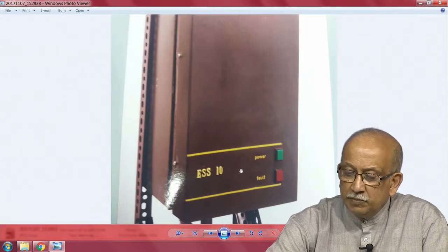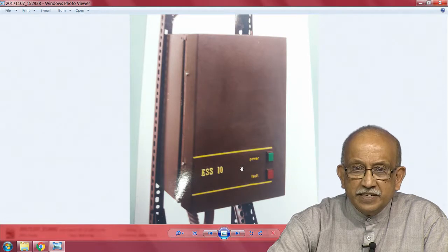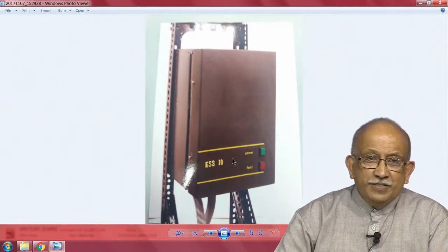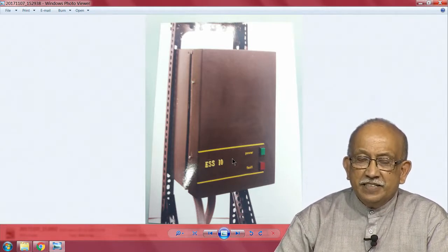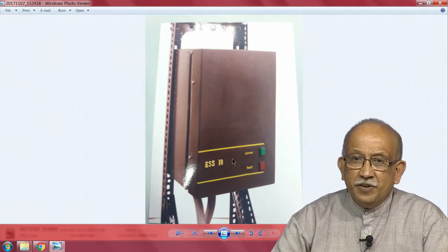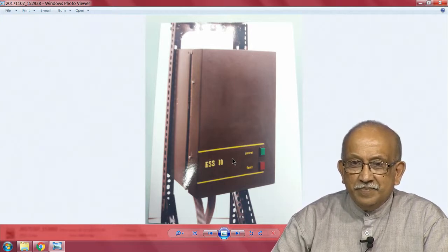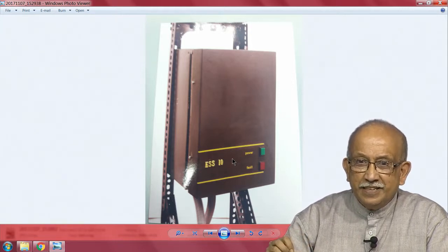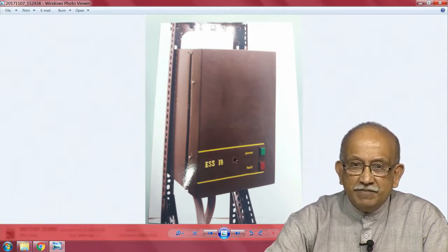I do not know, it may be a slow start or soft starter device, maybe for 10 kilowatts. So depending on your various requirements, we have a very neat control of the running of a motor, so that the current it draws is used only as torque and not in heating it up inside or trying to heat up the inertial element of it.